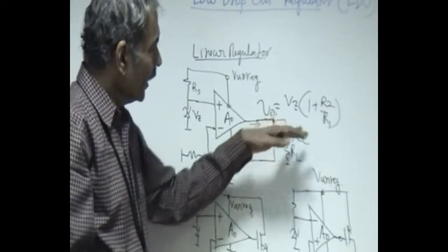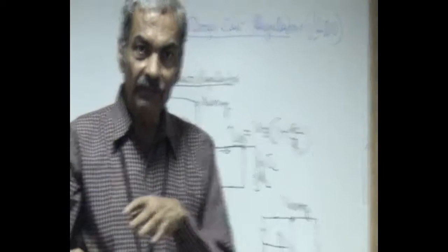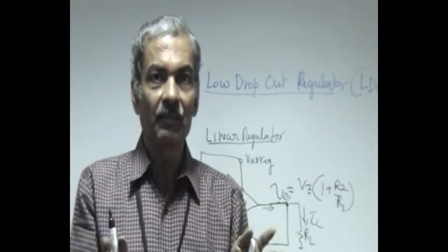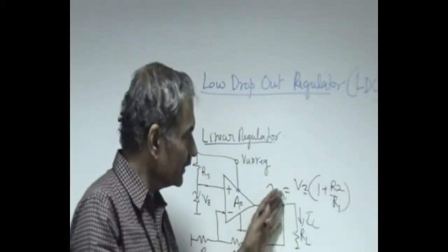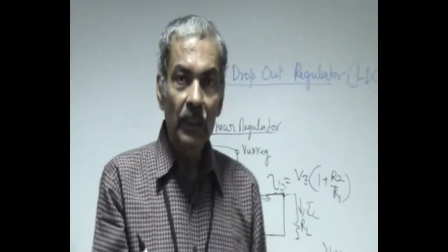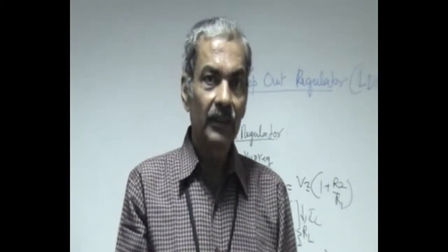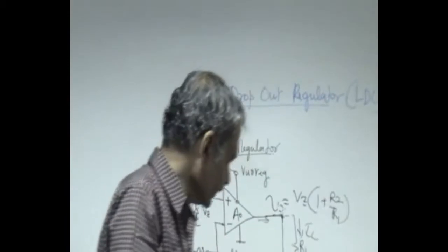And then the output impedance, which is a small signal parameter, has to be measured at the frequency at which this is supplying power, right? So if it is supplying power to, let us say, a high frequency stage, it is at that frequency that you have to measure the output impedance. That output impedance should be low, so that other circuits which are deriving power from the same supply do not get the feedback from this particular high frequency circuit that you are using.